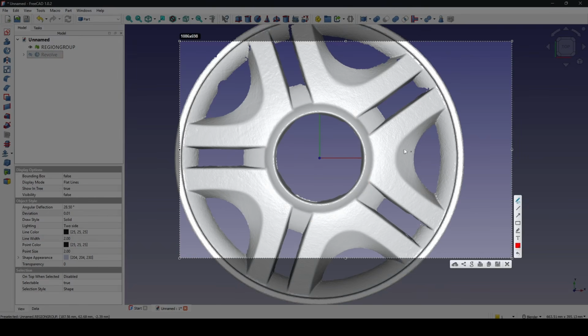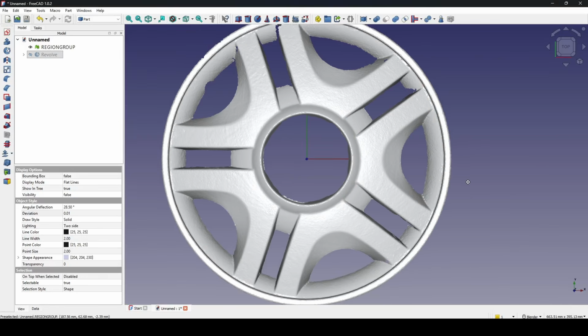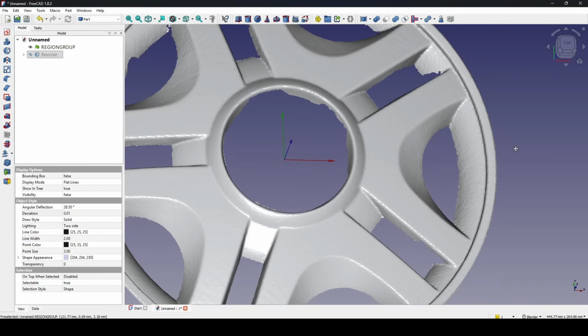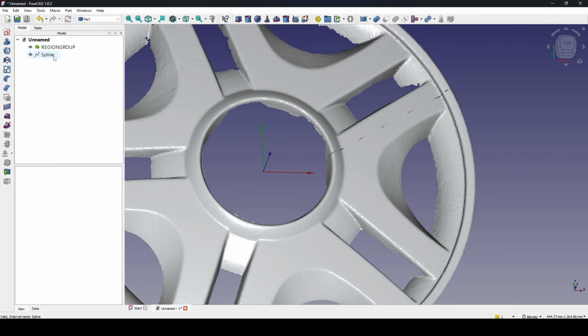I need to have a line in here. Okay, when I revolve, I need to have a line in here, and I also need a line in here, and another line in here, and another line in here. So basically, instead of revolving one big surface, I want my result to be the combination of many faces. Okay, so instead of showing like this, I will delete the revolve and delete the sketch.